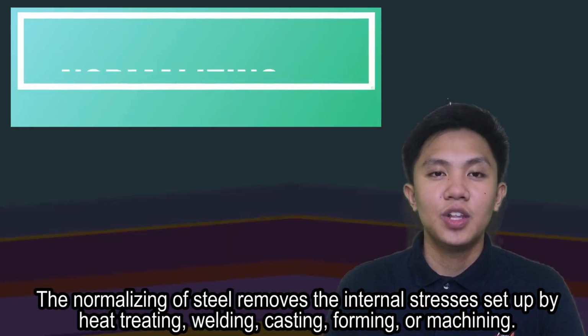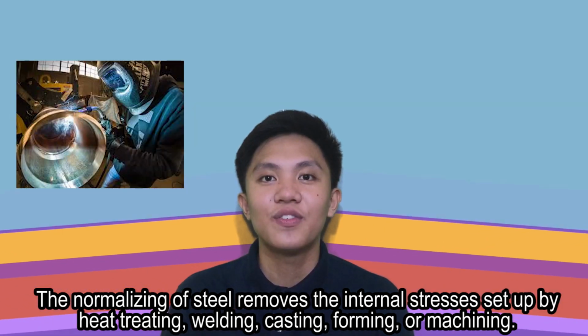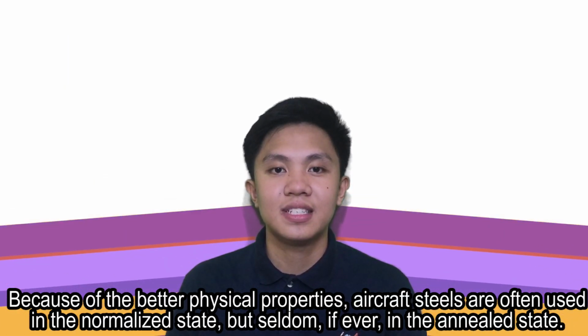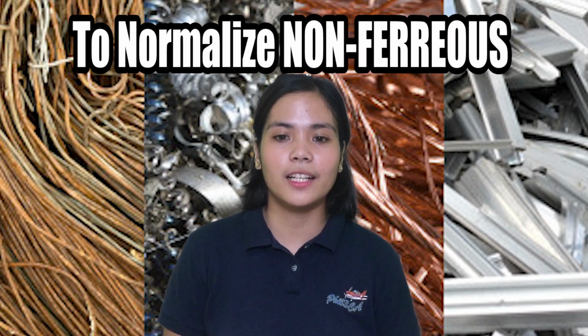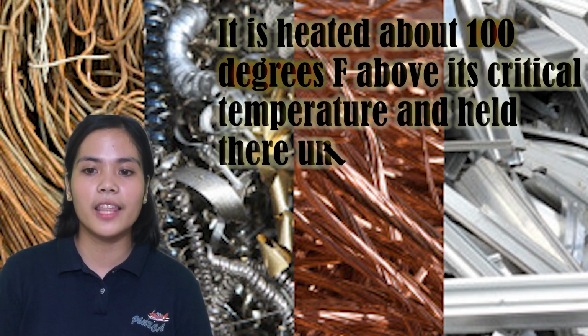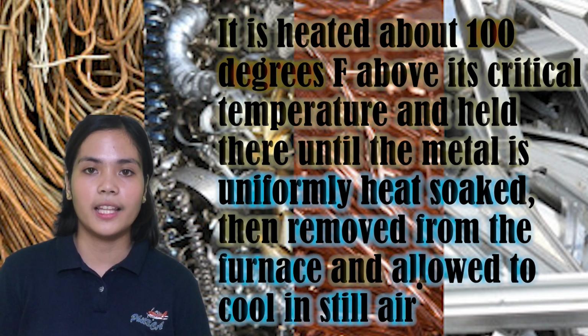How about if we accomplish it by heating the steel above the upper critical point and cooling it in still air? The normalizing of steel removes the internal stresses set up by heat treating, welding, forming, casting, or machining. Stress, if not controlled, will lead to failure. Because of the better physical properties, aircraft steels are often used in the normalized state, but seldom, if ever, in the annealed state. To normalize non-ferrous material, it is heated about 100 degrees Fahrenheit above its critical temperature, and held there until the metal is uniformly heat-soaked, then removed from the furnace and allowed to cool in still air.